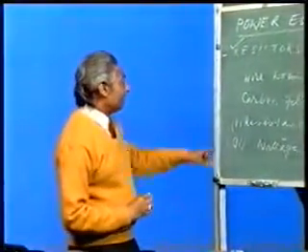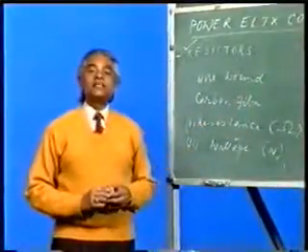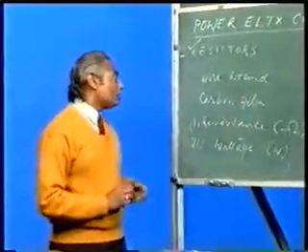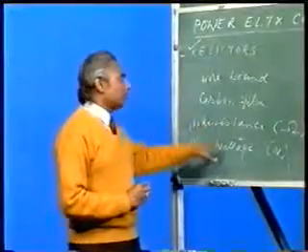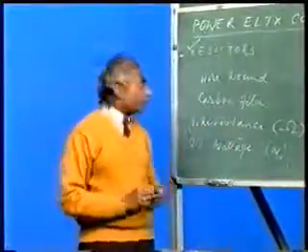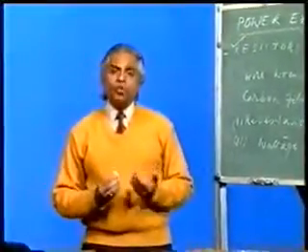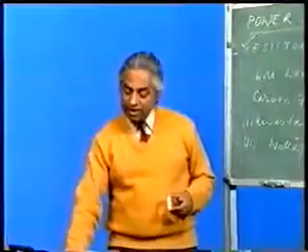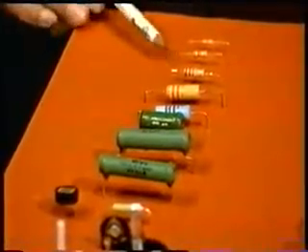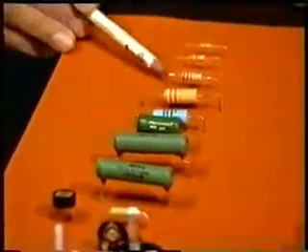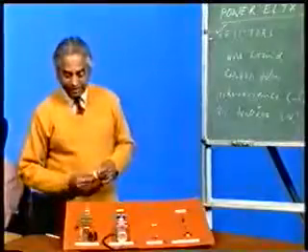Now there are methods by which we can find out what is the value of a resistor, similarly what is its wattage. The wattage means as you go higher and higher, it will have more bearing capacity of current. Here you can see this is a very thin resistor, then thicker, thicker, and so on. This is a quarter watt resistor, half watt, 1 watt, 2 watt, 5 watts, and so on. So this thickness of a resistor shows what is its wattage.